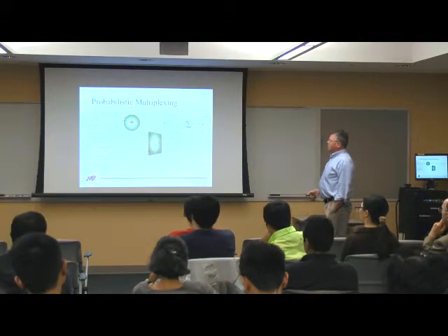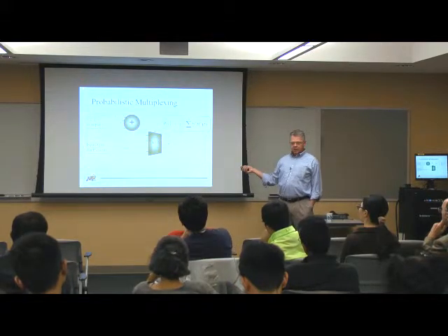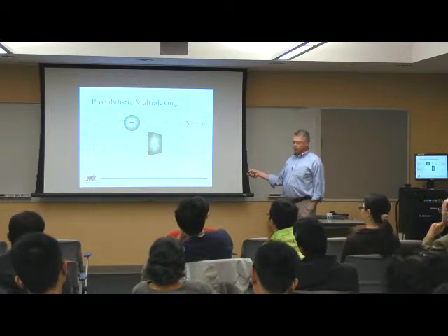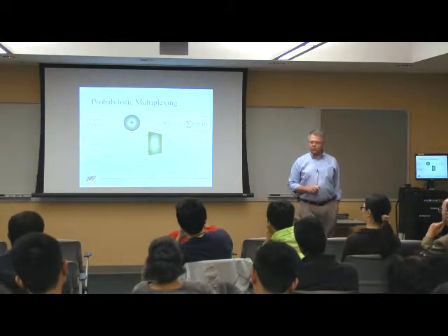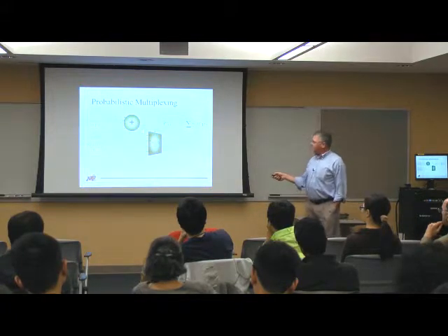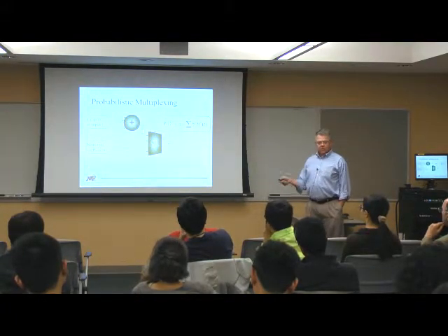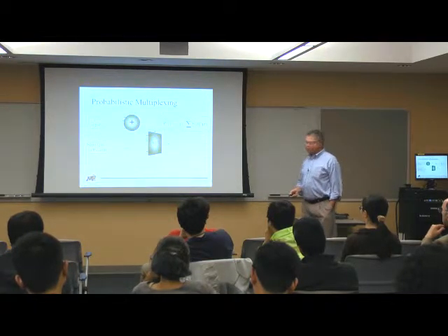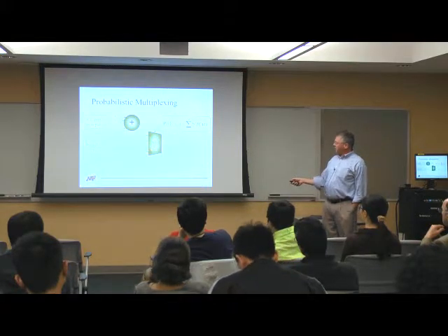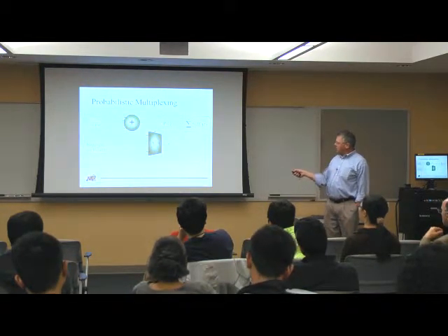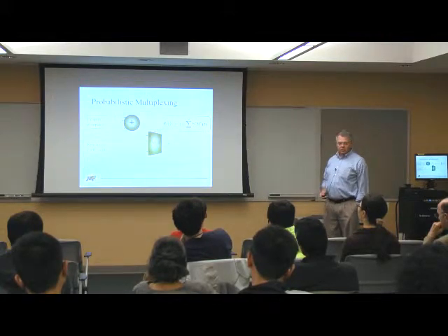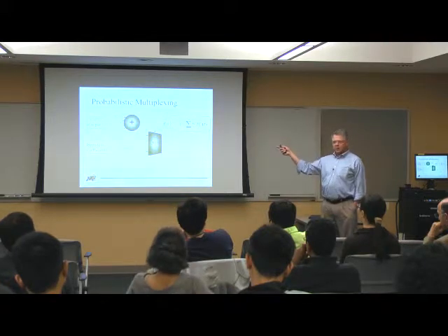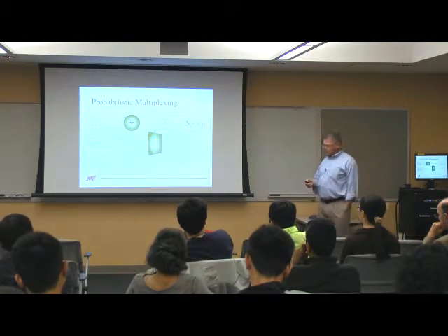All right? So this is what the circuit looks like when I'm done. I have the summation where I have n copies of the input t. And this gets to your question of, do the inputs need to be independent? Yes. If I need more than one copy of the input, then I have to have an independent copy of that input. So here I need n independent copies of the input t. And then I put my Bernstein coefficients in here, and the output is just that Bernstein polynomial. And I've chosen these coefficients to approximate whatever polynomial that I'm interested in.